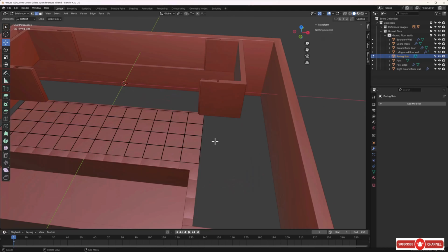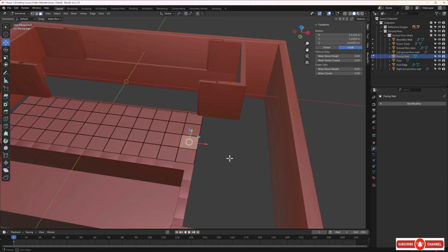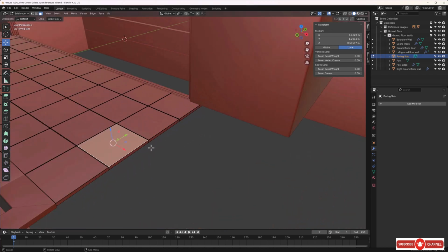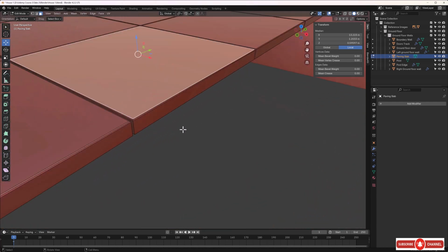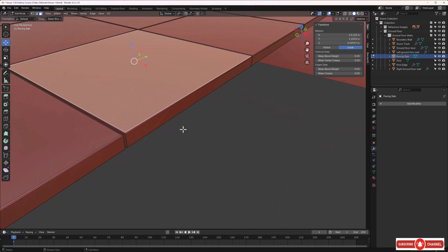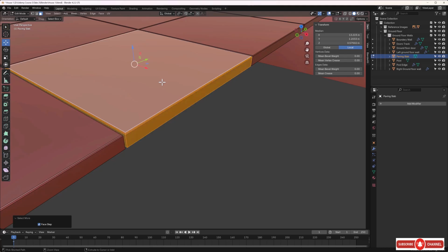So let's tap into edit mode, and let's press 3 so we can select faces. We'll grab this face here. Anyone will do, really. And I want to show you a new trick. I want to expand on this selection of this paving slab. So I'll hold down Control and then start tapping plus on the numpad. And you can see there that it's expanding on the selection. I can carry on plussing, but it won't go any further because it's reached the boundaries of that component. So we've selected all the faces now of that component.